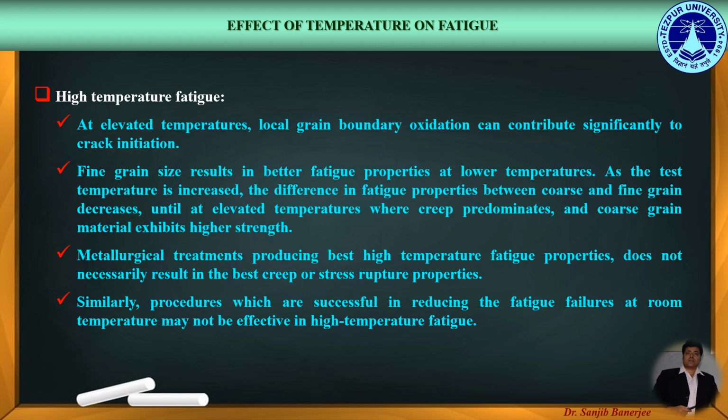Fine grain size results in better fatigue properties at lower temperatures. As the test temperature is increased, the difference in fatigue properties between coarse and fine grain actually decreases until we come at elevated temperatures where creep predominates and coarse grain material exhibits higher strength.